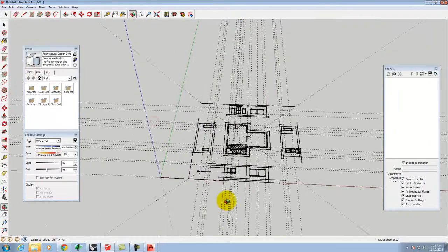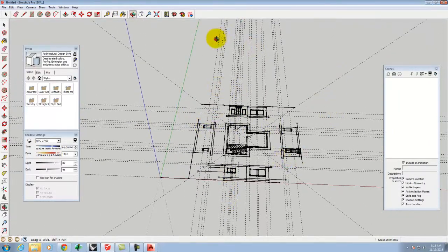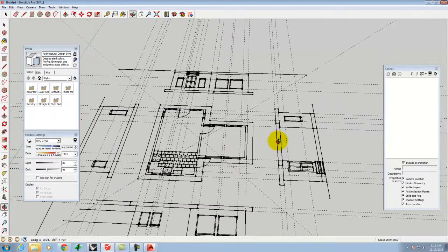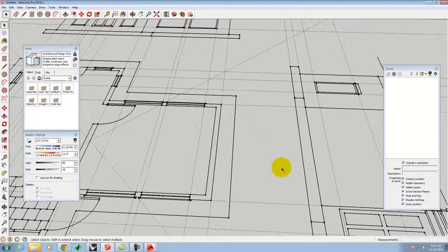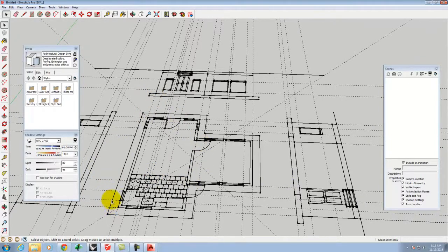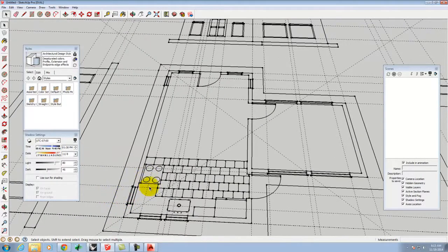So when it comes in, all of those rays that I created end up being guidelines, right? And all of the lines that I created are actual lines in SketchUp. So if we look at those, here's all our lines. Now, unfortunately, I can't really work in 3D with these lines just yet because they're not actually surfaces. And so I need to work through creating a surface for these particular pieces.